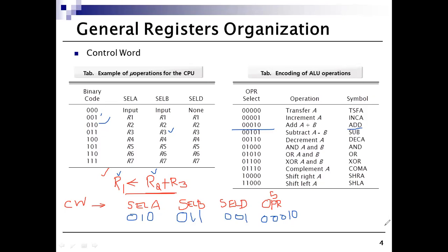These 4 control selection lines are selection variables. You can generate them by using hardware, or by using a control word sequence stored in a control memory, which we call a micro programmed control unit. Either of the 2 ways you can generate the required control selection inputs.